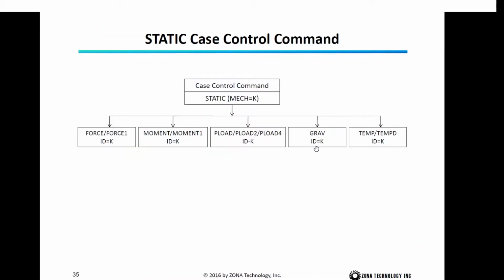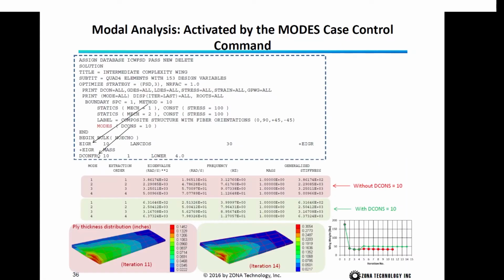And so the STATICS case control command can refer to FORCE and FORCE1, or MOMENT and MOMENT1, PLOAD2, PLOAD4. This is for imposing the gravity force. This is the temperature induced stress. And modal analysis is activated by the MODES case control command.